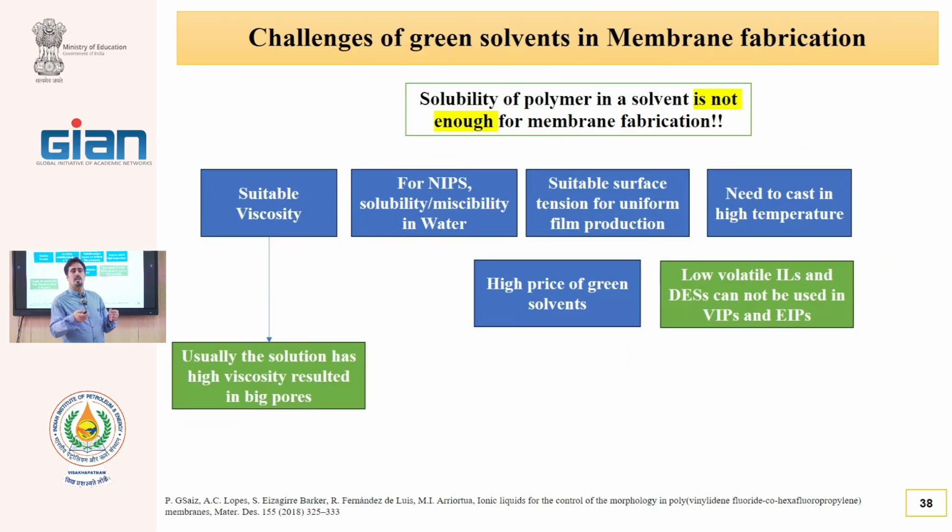And when we use a low polymer concentration, the resulting membrane is very porous. And when it is very porous, the stability and durability are low, and the mechanical strength is reduced.